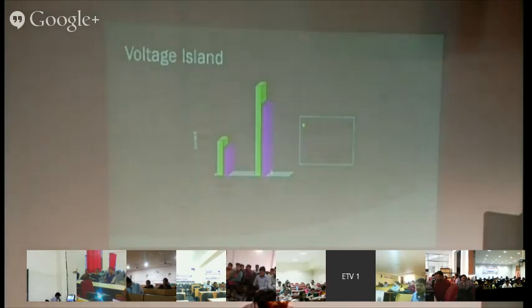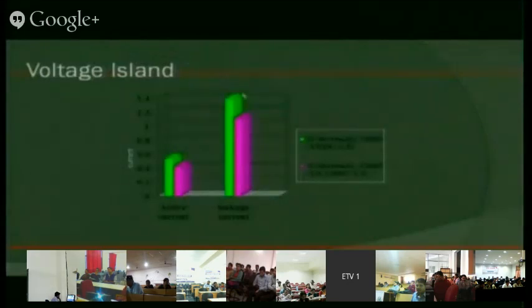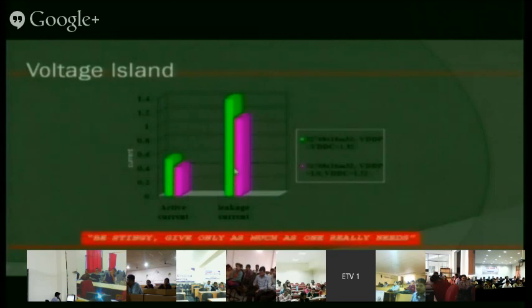So when you reduce the voltages, you get some saving in the leakages, and you get some saving in the active also. This is for two only. If there are 3 or 4 voltage islands, you will get further reduction. So where how much voltage is needed, give that voltage, don't give extra.